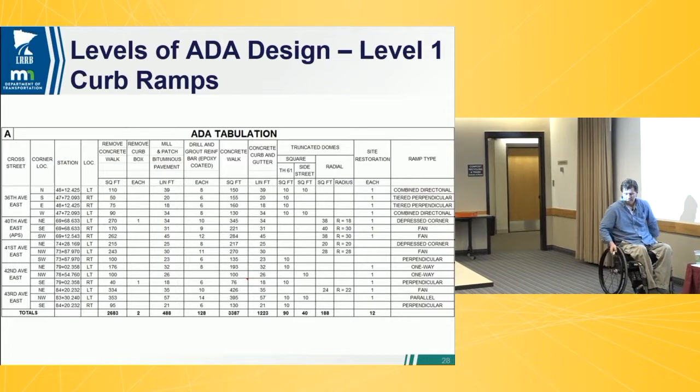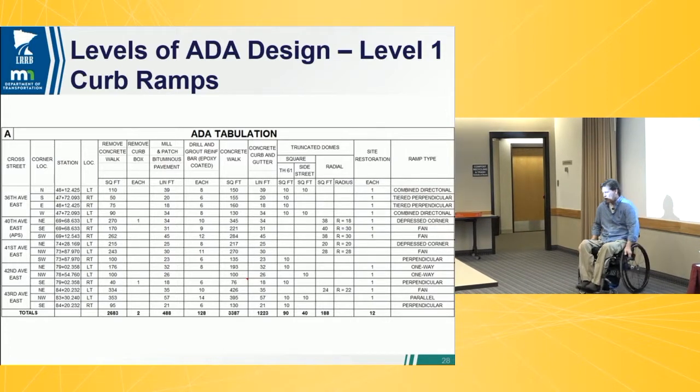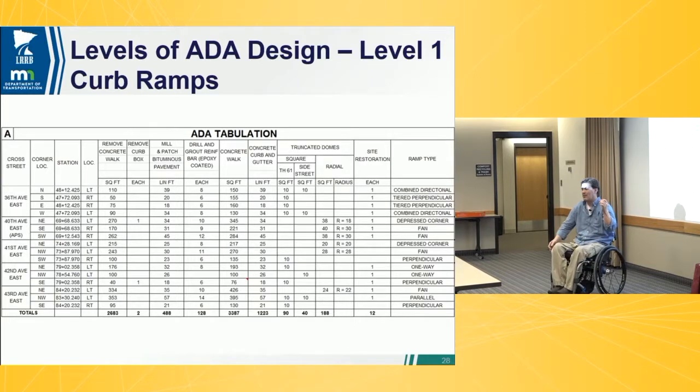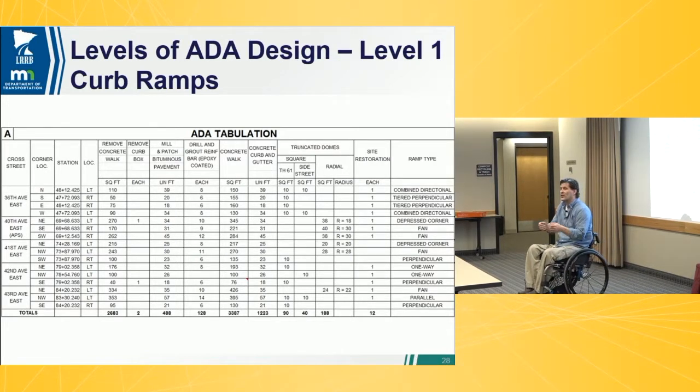Fairly simple. And actually, I had a project that came in at 90% plans, and they weren't doing curb ramps. And I know we missed some because they were out there. We were supposed to be doing them. So the designer kind of said, well, it's way too late now because I need to get surveys, I got to design it, got to get reviews, and it's never going to happen. I need 2 months minimum for this to happen. So I said, no, we can do better than that. So I went out there myself, 3 intersections, measured up 12 curb ramps by myself, just tape measure, slopes, figure out construction limits. 2 hours, had the quantities handwritten down, sent it to him, put them in the tabs, it was done. So it doesn't always have to be an ordeal.